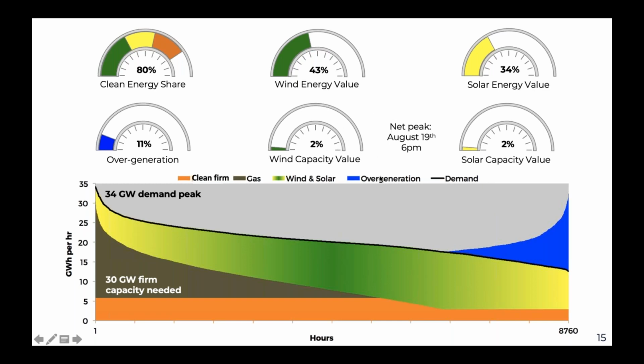And at the same time, it has a higher energy value because the bulk of the generation from the firm source can be dispatched in the periods when natural gas is consuming. Here, I assume that a nuclear plant, for example, can only ramp down to a portion of its output, so we had to keep it running at half of its output in these periods. So that's why it doesn't go all the way to 0. It depends on the technology you select, how flexible it is.